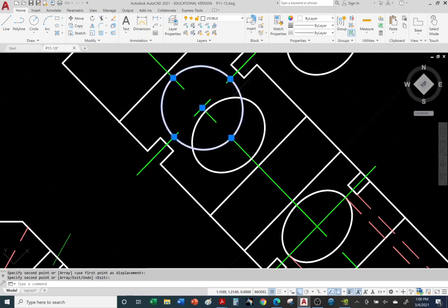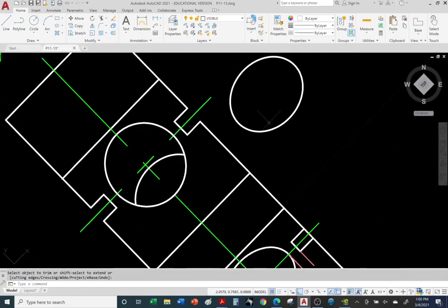Okay, so I'm going to use this ellipse to trim the other one. So I'm going to pre-select it as our cutting element. Then I'm going to click on the scissors, click. And then I'm going to remove the bottom portion. See that? I can remove the top, but I'm going to remove the bottom. Click and enter. Ta-da! Okay, now let's move this one back.